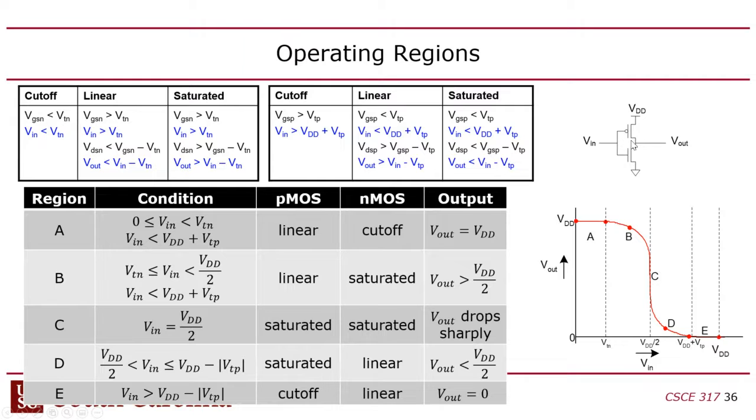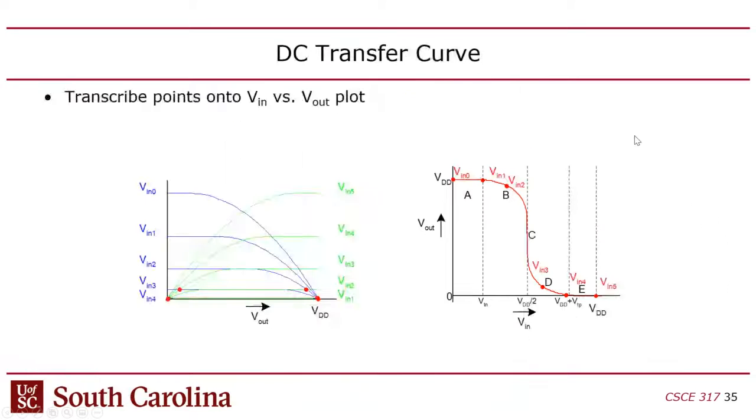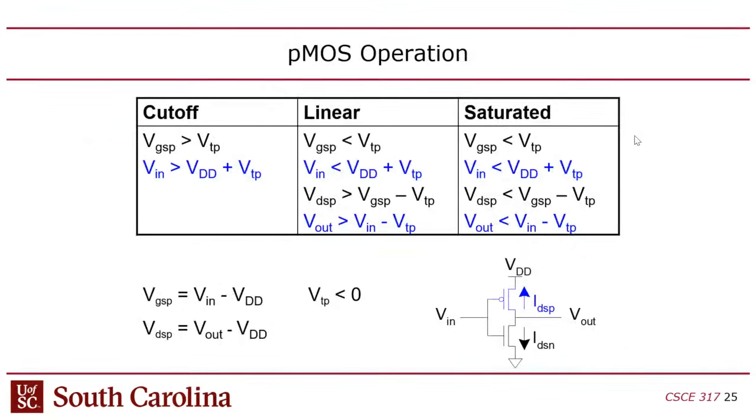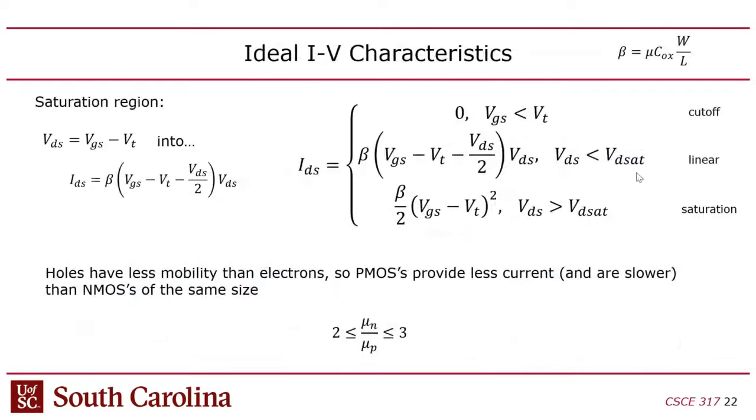Because the PMOS charge carriers are not as good. So typically, you design the PMOSs to be twice the width in order for the beta terms to be equal, but usually that's not quite good enough, because the mobility is between 2 and 3 times less on the PMOS.